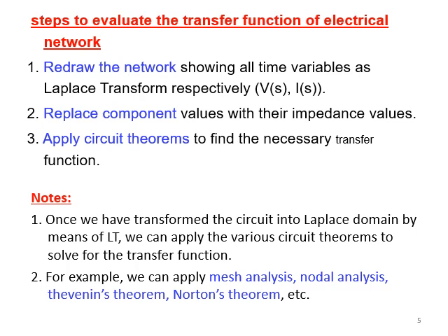What are the steps we are going to follow to model the electrical network? Whenever we get an electrical network or circuit, we will put it in the Laplace domain. That means we are going to remove all the element values expressed in the time domain and replace them with the equivalents as explained in the table on the slide given before.